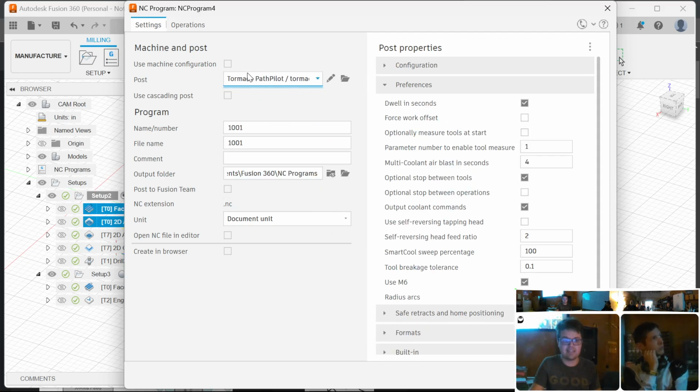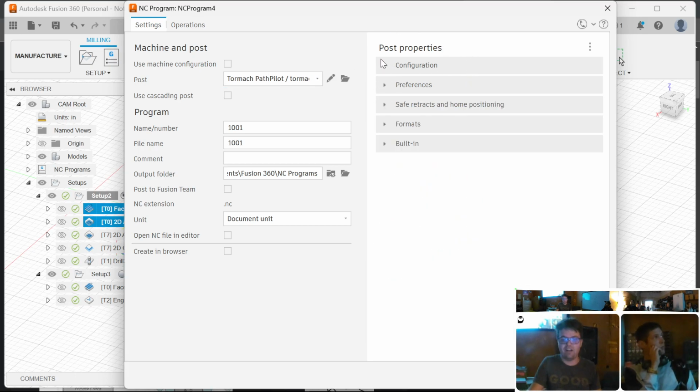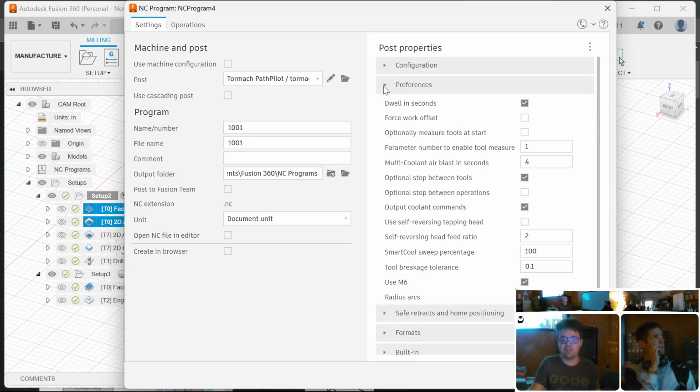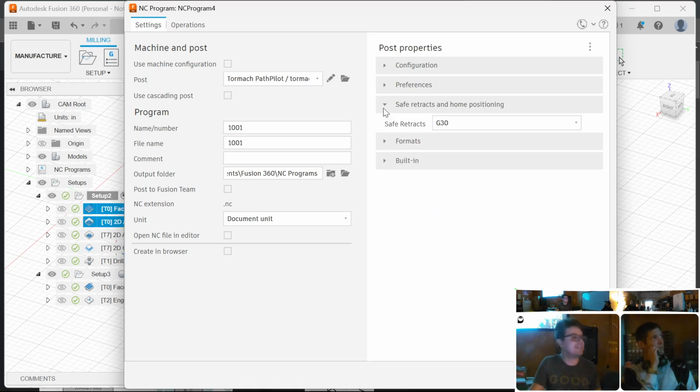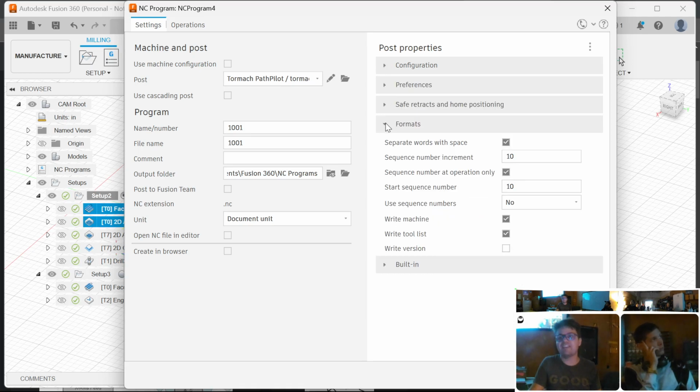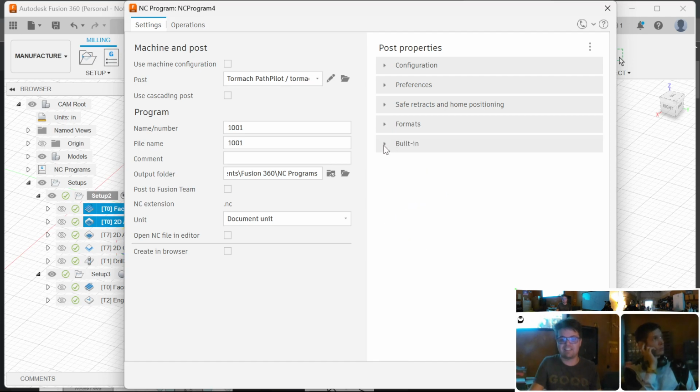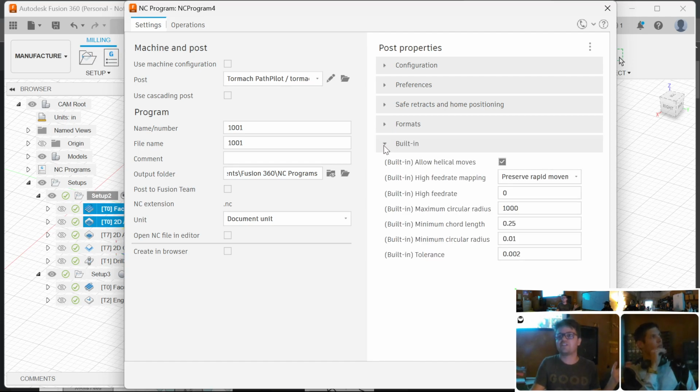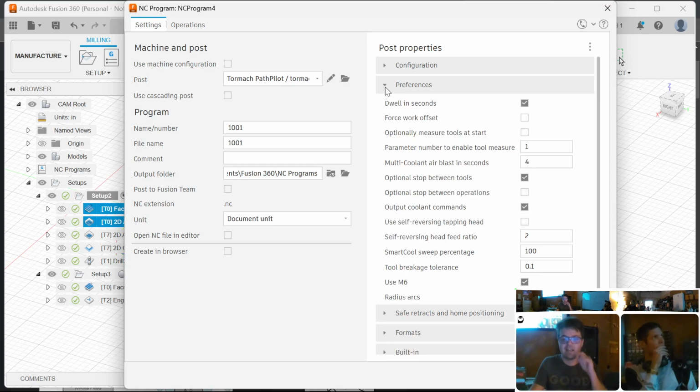When you select any one of these, it then generates a whole pile of post-process configuration settings that are machine specific, in case your machine has slightly different variants and different controls and you want to change slightly how the G-code is generated. Some of these matter a lot, like when you're generating for the ShopBot, you have to tell it that the ShopBot doesn't have a tool changer because it will otherwise generate tool change commands.